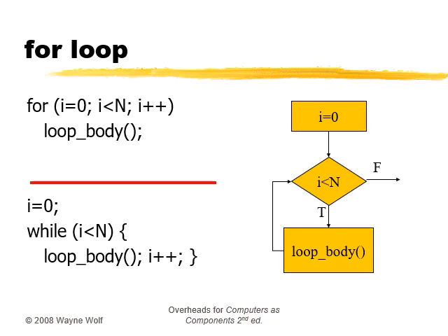So again in this slide we have a description of control data flow graph. Here we have some data, here we have some data. So these are encapsulated data flow graphs. Here we are doing a decision, so that is our decision node. Initially i is equal to 0, if i is less than n, we are going to execute the body of the loop, and once it is done, we go back and check the statement again whether i is less than n or not. Same thing goes for a while or for loop. We can use this CDFG. So let's move on to the next slide.